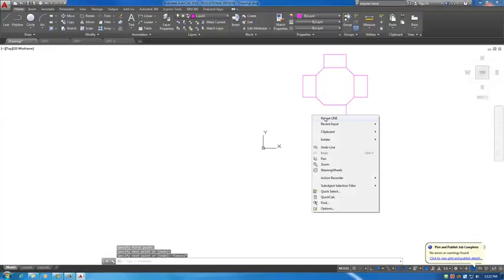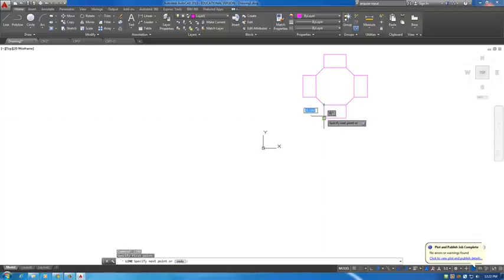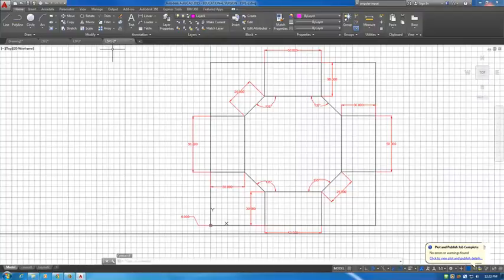Notice how I use the repeat line tool there. It's just a quicker way rather than going over to the side of the screen to repeat your last command. Okay, so that's our base, the center here. I'm going to let you guys figure out how to do the outside. There's multiple ways you can draw lines from here and then trim them off later where they intersect, or however you want to do it. Okay, I'll let you guys figure that one out. But so that's using coordinates to get us started, and then using angular definitions to define 45-degree angles.